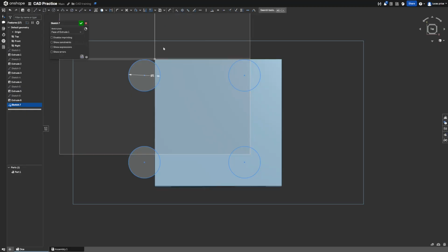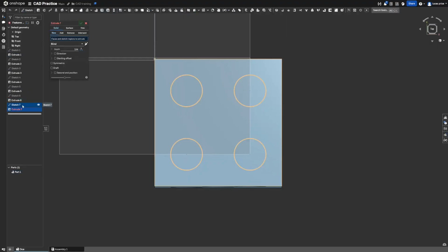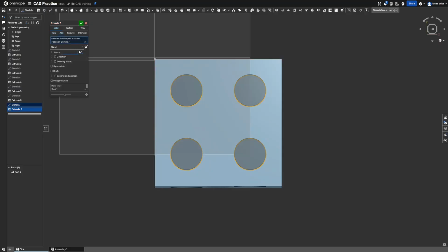And now I'm just going to drag these over a little bit. Just dimension them how you normally would. It should auto adjust most of them for you, might have to do a little bit of tuning. And then if you're wondering why one is blue still, you can just drag it and see, okay, I need to dimension it this way. So I see that and I just go here and dimension this, and now it's all white. And we will remove this 0.25.